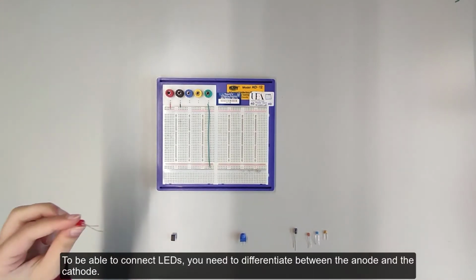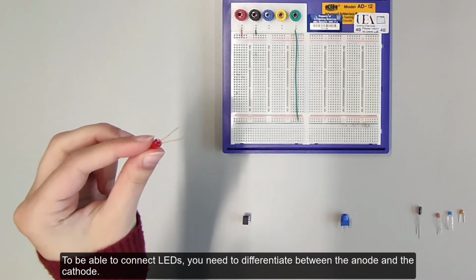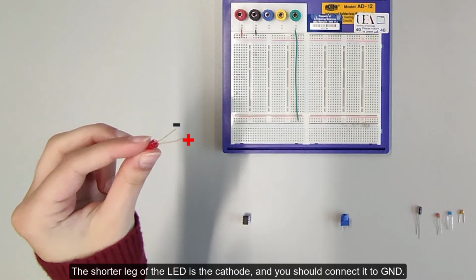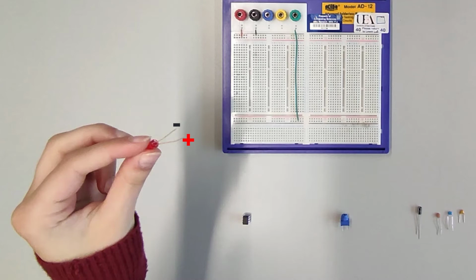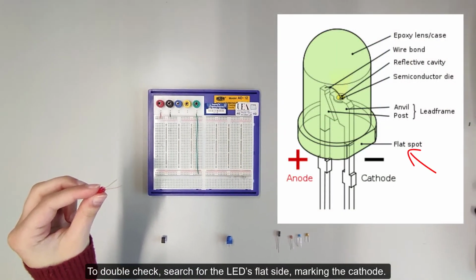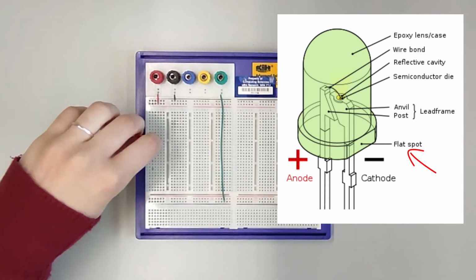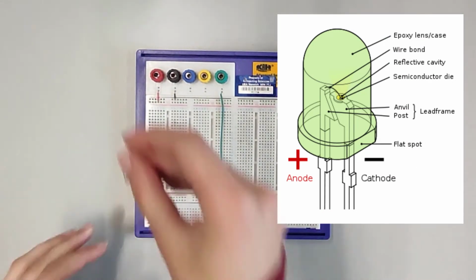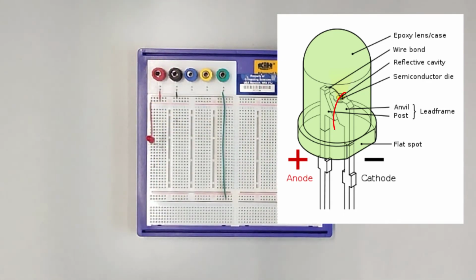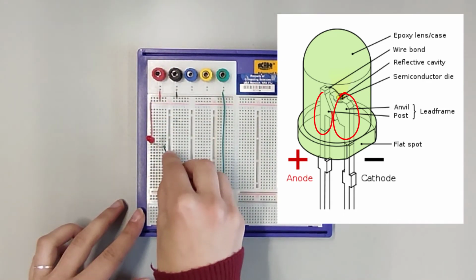To be able to connect LEDs, you need to differentiate between the anode and the cathode. The shorter leg of the LED is the cathode and you should connect it to ground. The longer pin is the anode and should be connected to positive power. To double check, search for the LED's flat side marking the cathode. You can also tell the pins by looking inside the LED. There are 2 structures separated by a space. The biggest structure is the cathode and the other one is the anode.